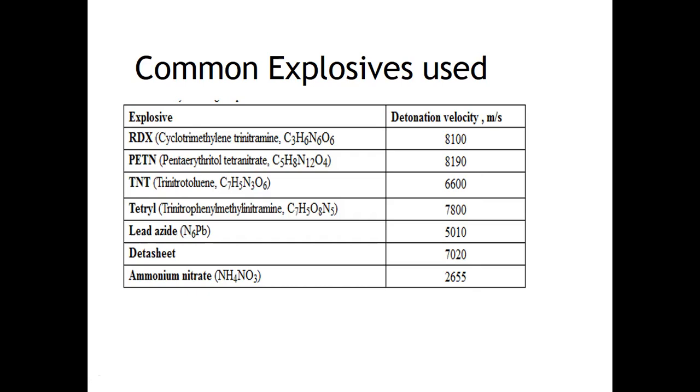You can decide what type of explosive to use based on the material you are trying to weld and the quality of weld that you want. Basically, the material will decide whether it can take the strength or not, and the gap that is there. All these are factors to choose the explosive.